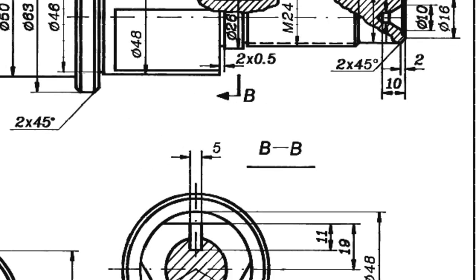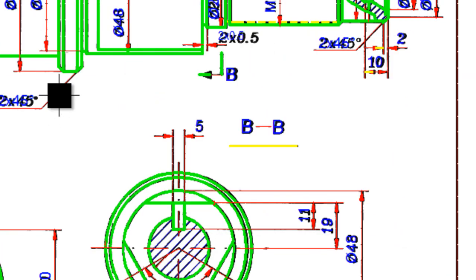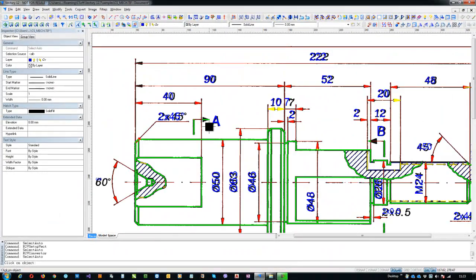Now I have a button on this one. I can say the raster-to-vector. I have the same button on this toolbar. I can click the raster-to-vector, so things will be converted into vector. Depending upon the quality of the input, you will receive the conversion results. So you need to verify the results.